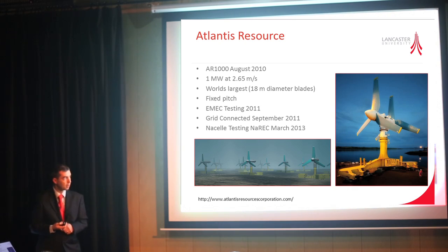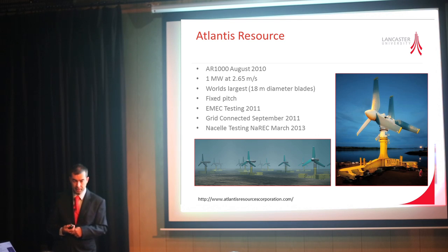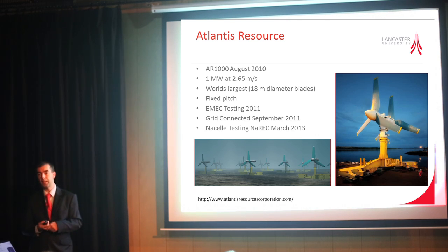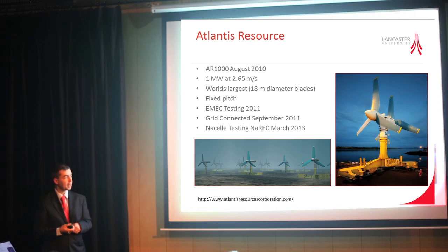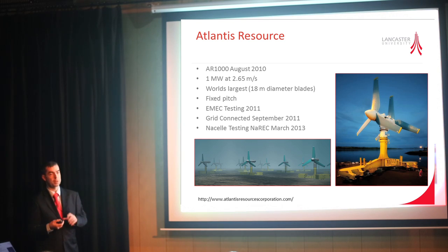Atlantis Resource, again horizontal axis. This time they have a fixed pitch blade. So rather than having variable pitch like Marine Current Turbines, they have a fixed pitch arrangement, and they've gone for a twin rotor design initially, where one rotor takes the flow in one direction, and then the second rotor takes the flow in the opposite direction. So as the tide changes and comes in and out on the ebb and flow, they have a different rotor to take the power off each time.